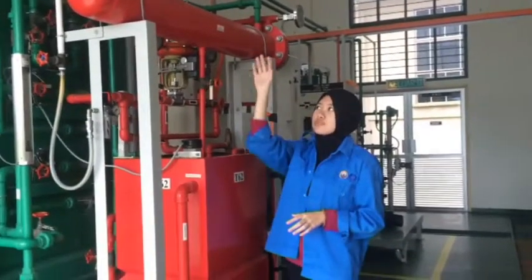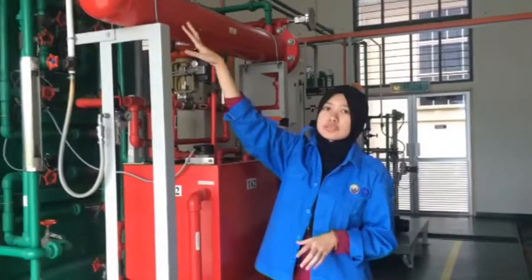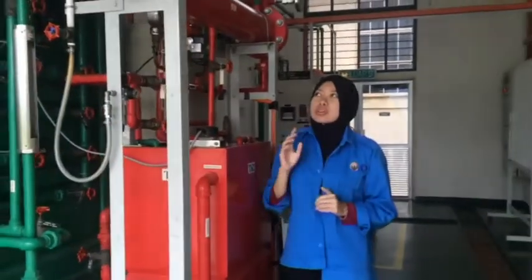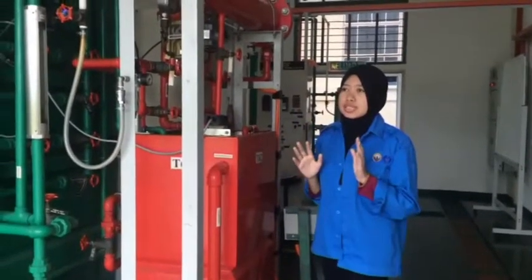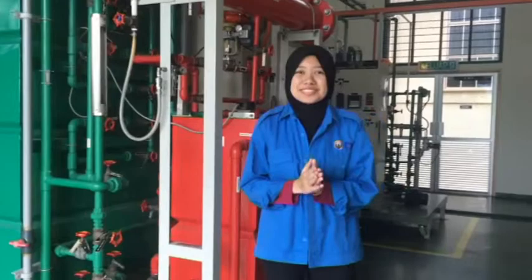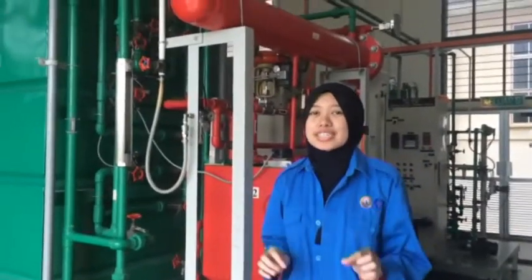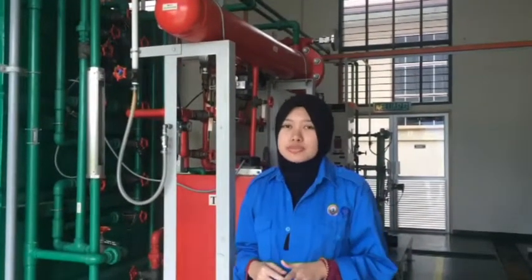The hot hydraulic fluid will flow in the baffle, and the cooling water will flow into the bundle of tubes. Basically, in a heat transfer system, heat is exchanged as two liquids of unequal temperature approach equilibrium, and a higher temperature difference results in a more rapid heat transfer.